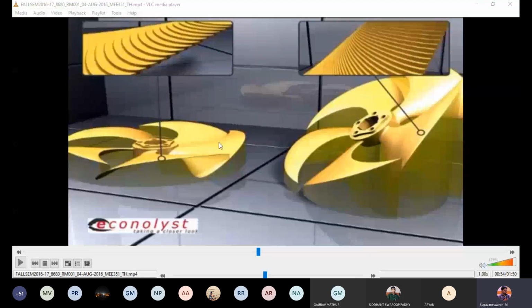For example, the cost of the first printing will be less than the second printing because though I will be consuming the same material for the part, the support requirement will be very less. So obviously the cost of the first will be less than the second. But if you look into the finish, for example, the inclined surface is shown here. The close-up view of the inclined surface is shown here. Here also the close-up view of the inclined surface. As I deposit material layer by layer, there is an effect called the staircase effect. So whatever you can see from the video is nothing but a staircase.